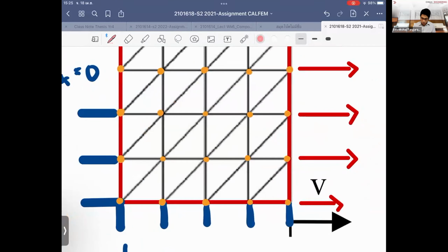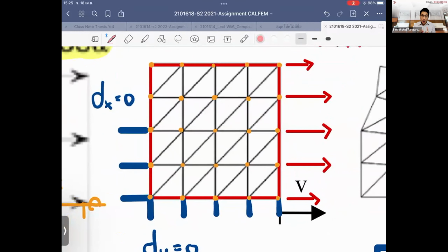So you start from the mesh, and the only thing it cares about is how you orientate the order of the nodes in the element. So, right, the direction that you start at the start node, and you keep rotating the node to form the rectangle elements, you should follow the same order for all the mesh you're looking at in the problem, right?